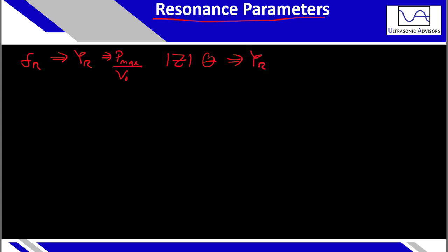So the real admittance is equal to 1 over the impedance magnitude multiplied by cosine of the phase. If you say this is the impedance phase, technically you have to take the opposite of that for admittance, but because you're using a cosine, it doesn't matter.